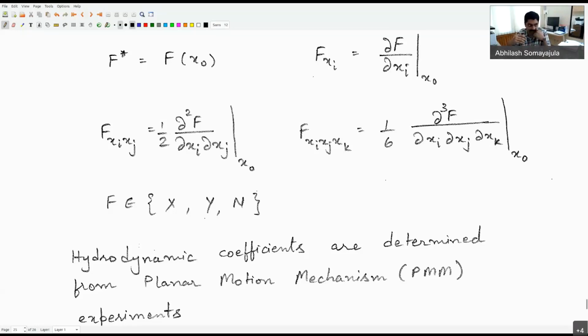It's much more intuitive to port those drag coefficient values from one ship to the other, rather than porting the actual hydrodynamic coefficients from one ship to the other. Because the hydrodynamic coefficients strongly depend on the geometry of the vessel, but the drag coefficient also depends on the geometry of the vessel, but you can make a grosser approximation on it.